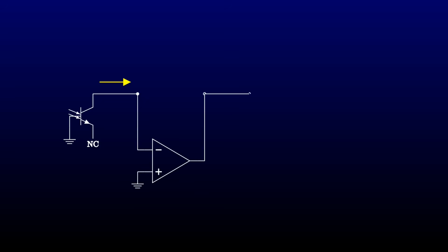It'll arrive at the summing junction of an op-amp inverting amplifier. The summing node is virtual ground, and so there will be an extremely low impedance looking into it, which is what we want. We'll use an extremely large feedback resistor, say 10 megaohms. Since we assume the op-amp input draws no current, the current through the feedback resistor will have to balance the current at the input. A 1-volt output will correspond to a 100 nanoamp input, or in other words, the transresistance will be the same 10 megaohms. That should be enough to see how the circuit responds to light.